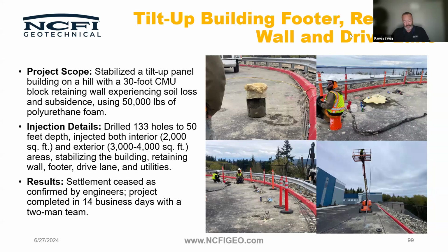Exactly. Isn't that kind of the point, though, to be aware, right? If you're in an injection situation and you've got way more material moving than what you were accounting for in the void, and you're just injecting all day long without getting any kind of bump or movement, then you might be aware that something might be happening. And there are injection techniques you can use to try and mitigate that from occurring, such as short shots, allowing it to cure and then doing another injection. But be aware of what's happening.